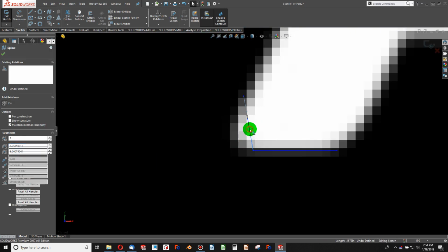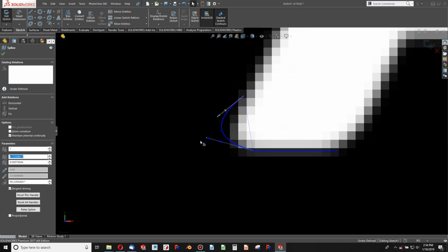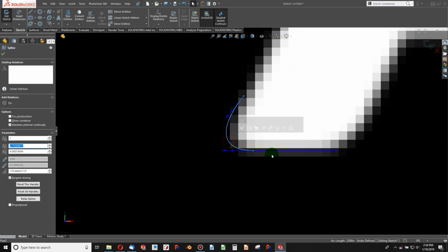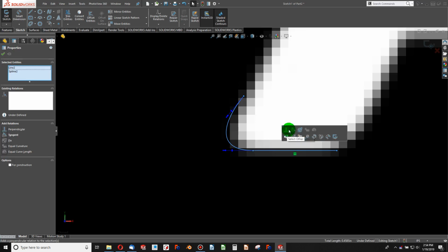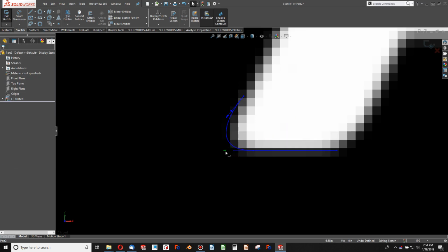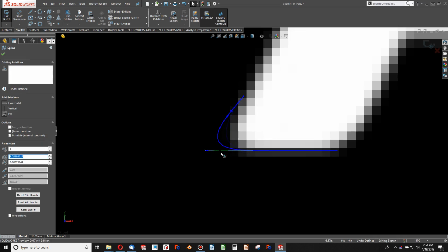And so if you want to have a lot of exactness, I recommend choosing two spline points. And notice I have a point here at the end of this arrow that I can adjust the spline with, and I have a point here. If I do more than 2 points, it gets a little bit more complicated, too complicated really to be exact with. I can add a tangent relation to my lines, which essentially just holds this arrow horizontal, and the length of the arrow determines the variable radius I'm putting on the spline. And then I can adjust the other one as well.